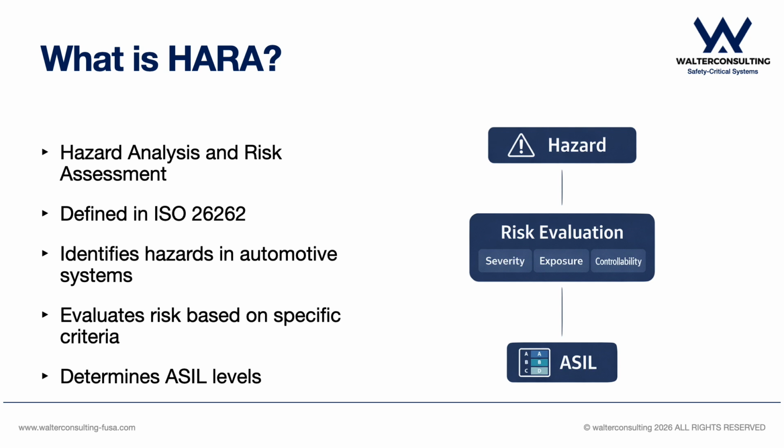Now, let's look at HARA. HARA stands for Hazard Analysis and Risk Assessment. It is defined in ISO 26262. HARA identifies hazards in automotive systems. It then evaluates the risk based on three factors: severity, exposure, and controllability. Based on this evaluation, an ASIL level is assigned. This determines the required safety measures.